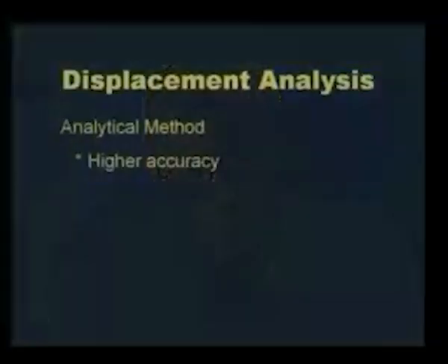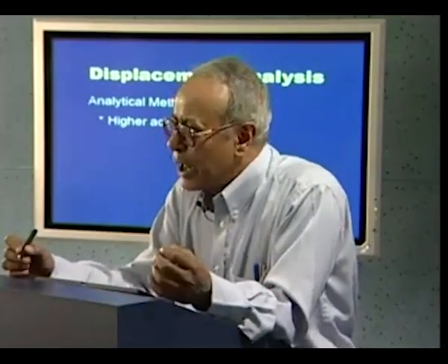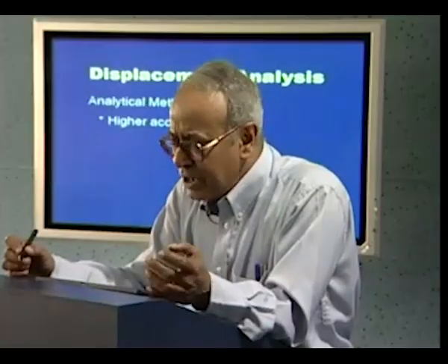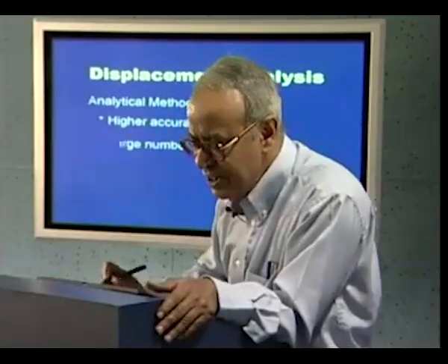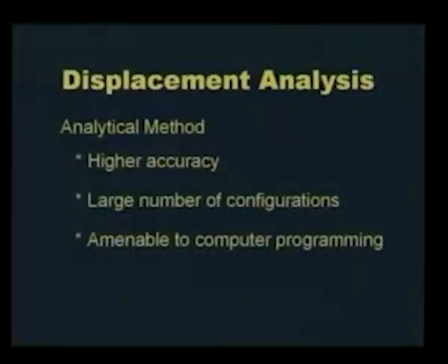Now, when do we use analytical method and when do we use graphical method? As we see, in the graphical method, there is an inherent limitation on the accuracy because of the scale of the figure and your drawing inaccuracies. So, analytical method is preferred when we want higher accuracy, or if the displacement analysis has to be carried out for a very large number of configurations, and in the graphical method, the picture becomes really cumbersome. And the other advantage of this analytical method is that it is amenable to computer programming.